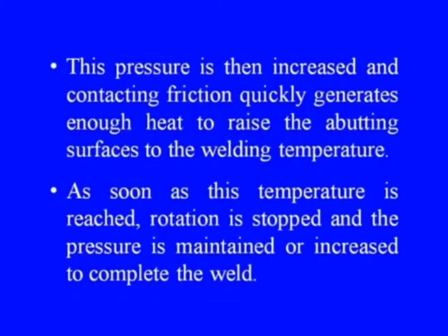This pressure is then increased and contacting friction quickly generates enough heat to raise the abutting surfaces to the welding temperature. As soon as this temperature is reached, rotation is stopped and the pressure is maintained or increased to complete the weld. This is another important condition.